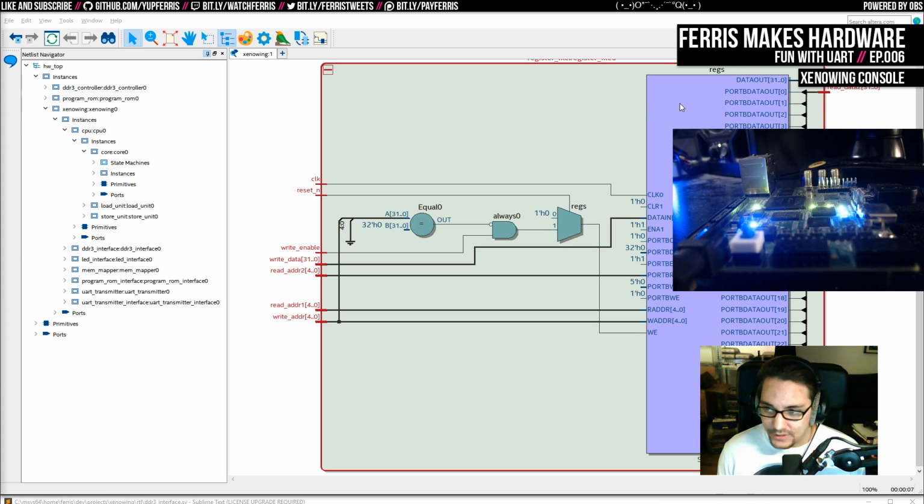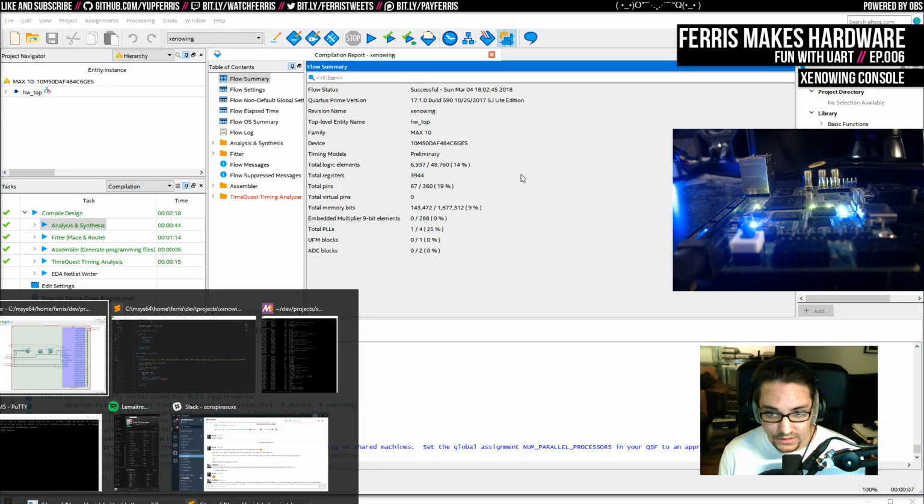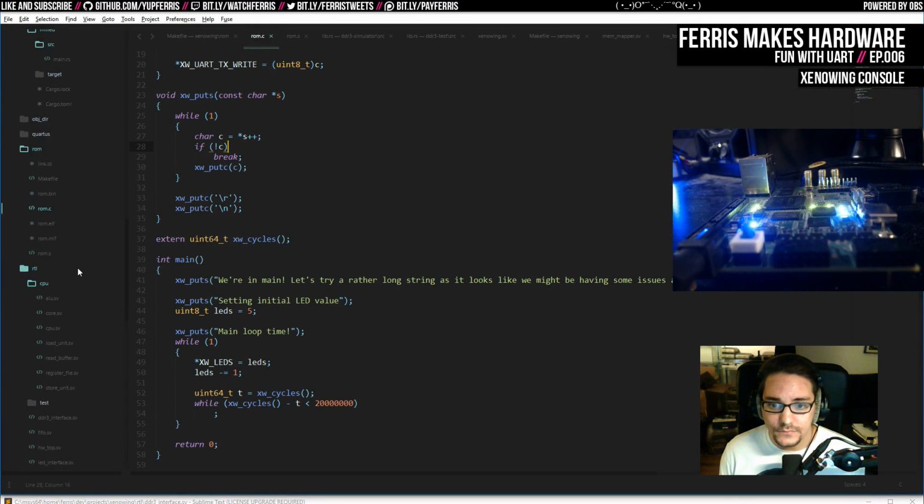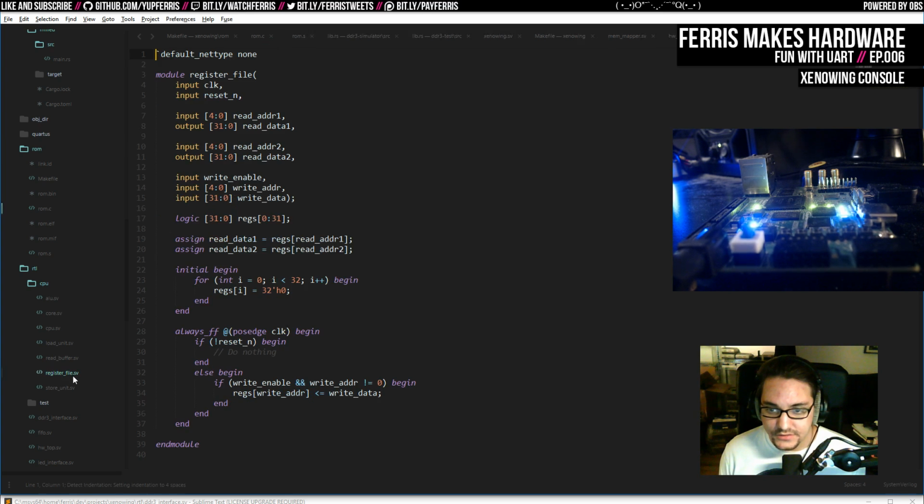Anyway, I think that when I left that, this was a little bit simpler because it didn't actually ensure that register 0 was 0 all the time. So what I ended up adding was a tiny bit of logic. I'll pull up the RTL for this. Where's my register file? Here. So I did a couple things here. The first one is this. When it's writing, it just won't write when the register address is 0. So that's trivial, obviously. Maybe I did that on stream.